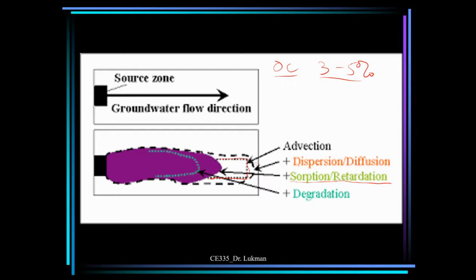But one thing for sure is that all soil has this. When you heat above 105, you expel the water, and when you heat further, you do away with the organics. These are called the organic content of soil.